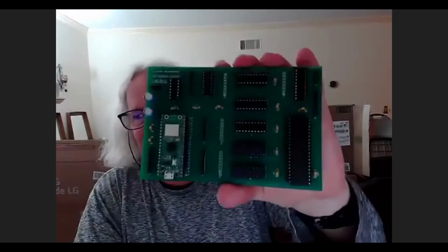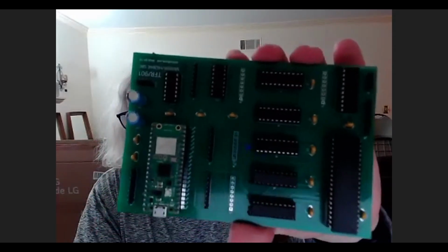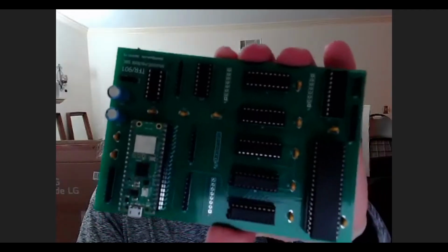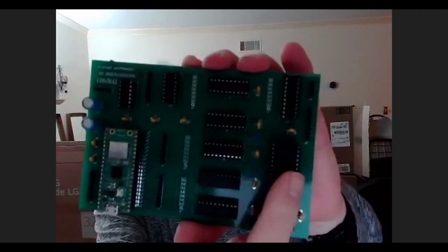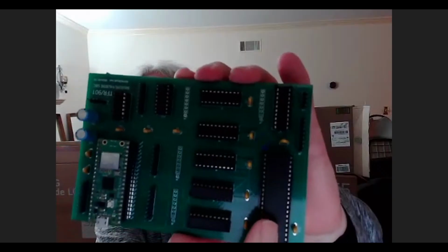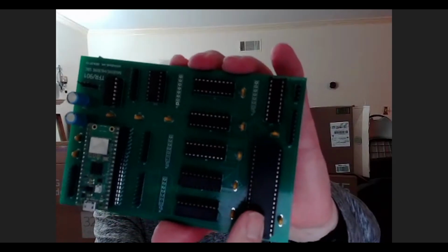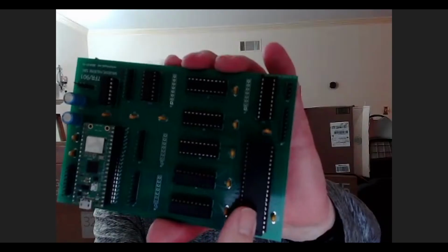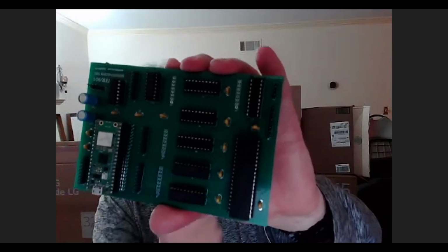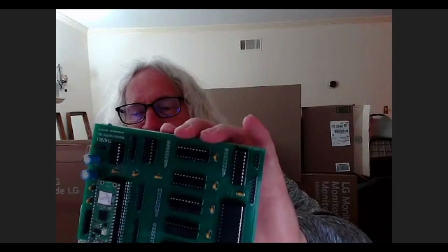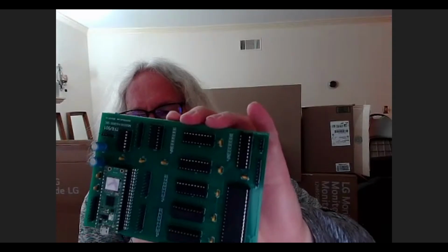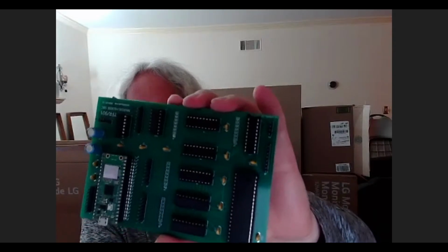So before I start showing you some slides, while I've got the camera on, I'm going to show you some boards. I'm building what I'm going to call a single board computer, because here's a single board. It's got a Hitachi 63C09E. The C means it's a 3 megahertz part. The E means that the clock is external, and that's going to be very important in this design.